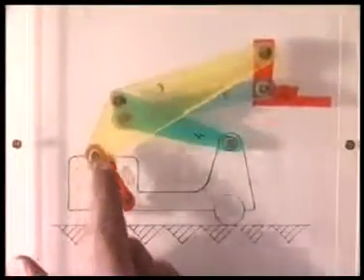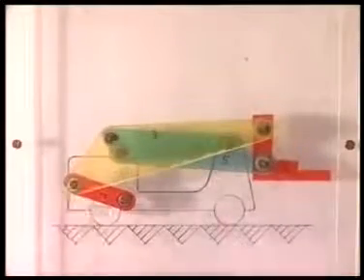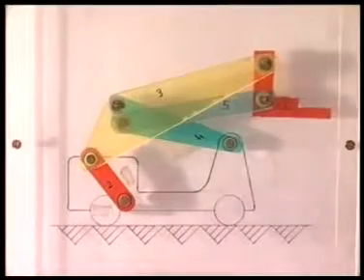So the techniques that we have learned for function generation, motion generation and path generation can be synthesized together to have a multi-stage synthesis problem for even more complicated problems. So in today's lecture, we have designed a 6-link forklifter using only revolute pairs by a multi-stage synthesis process, which are basically a combination of the 3-position synthesis for function, motion and path generation of 4-link mechanisms, which we had discussed earlier.